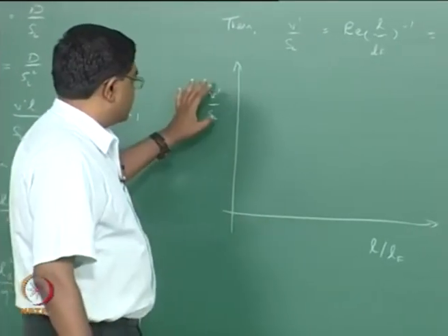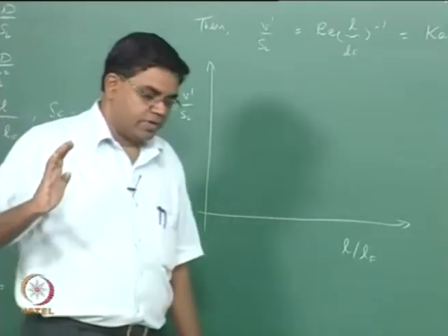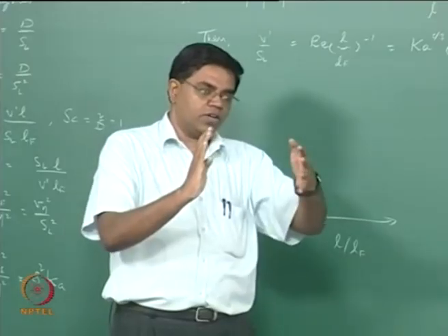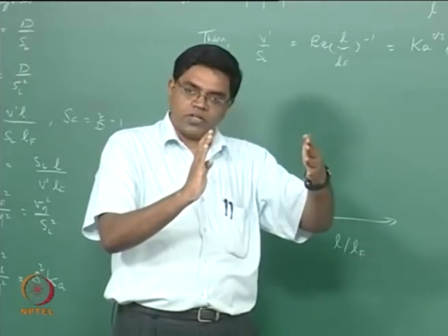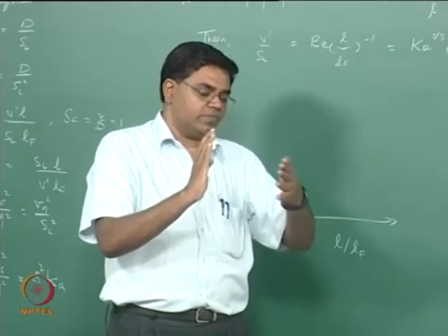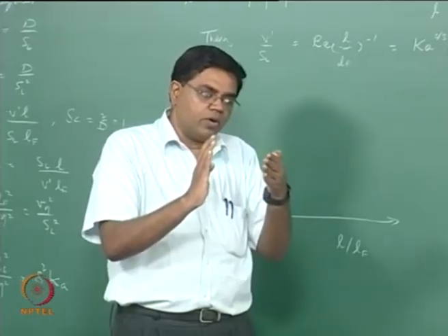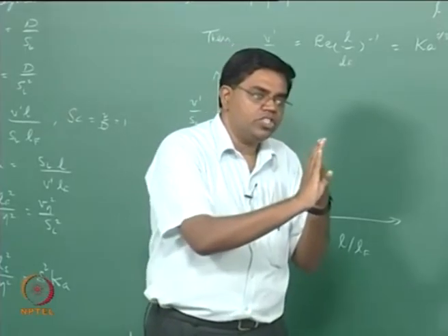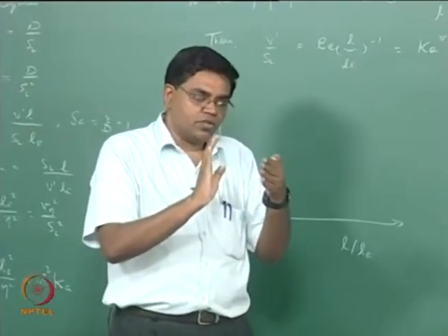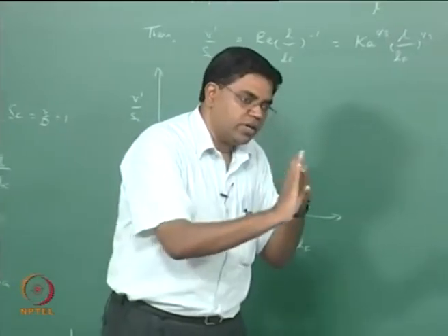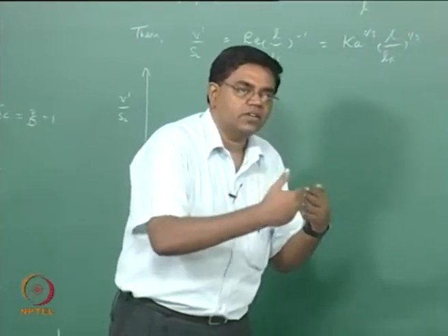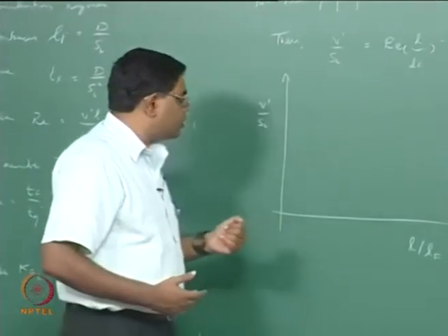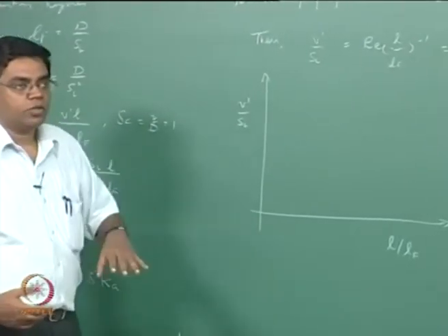As far as the intensity is concerned, when you have a flame that is trying to propagate at a particular speed, if the flow out there is fluctuating at a certain intensity, and the fluctuation is very small, then as the flame propagates it does not really go through any jitter. It is so small that the flame can just go through without even realizing that it went through a fluctuation. Then you do not really have a turbulent flow at all.